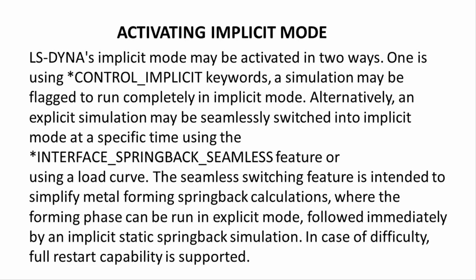The seamless switching feature is intended to simplify metal forming springback calculations, where the forming phase can be run in explicit mode, followed immediately by an implicit static springback simulation. In case of difficulty, full restart capability is supported.